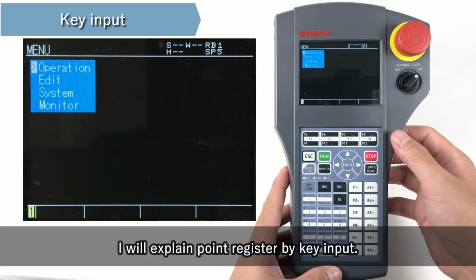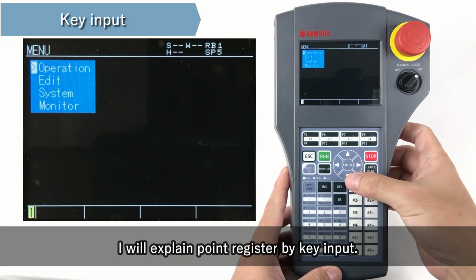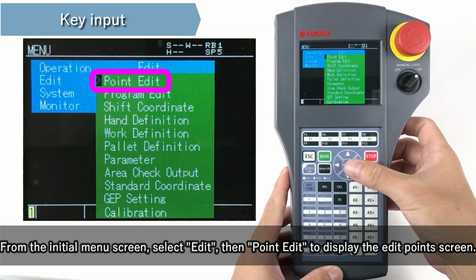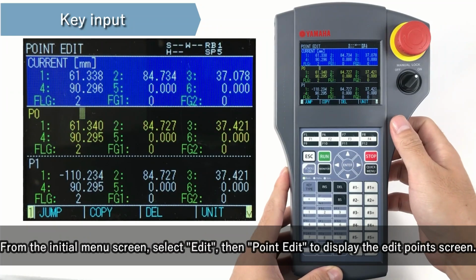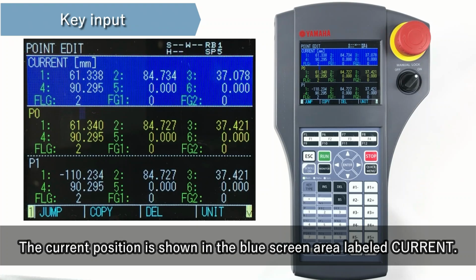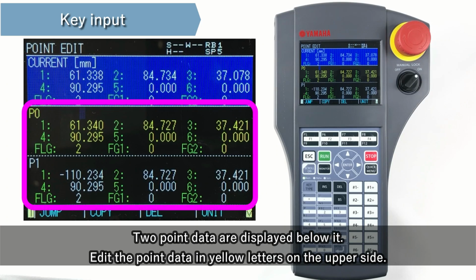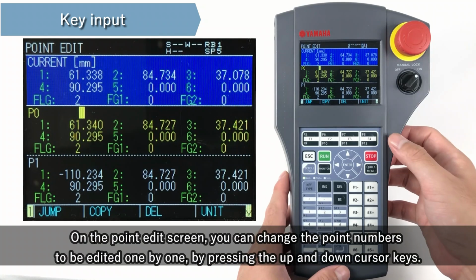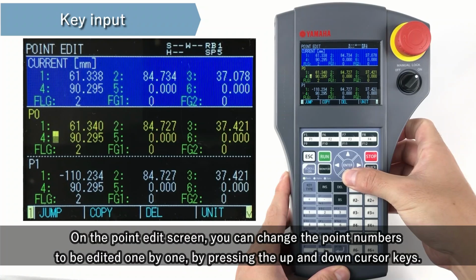I will explain point register by key input. From the initial menu screen, select Edit, then Point Edit to display the Edit Point screen. The current position is shown in the blue screen area labeled Current. 2 point data are displayed below it. Edit the point data in yellow letters on the upper side. On the Point Edit screen, you can change the point numbers to be edited one by one, by pressing the up and down cursor keys.